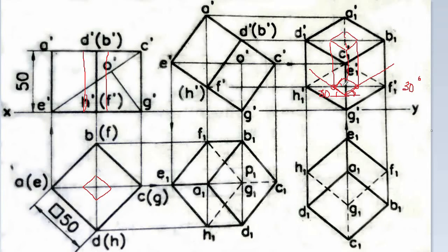After that, you take another 30 degree line. This angle is 30 degrees, and you can draw another two lines in both directions. Then you can project upwards, and you can mark the height. What about this height? This height will be 0.816 times the actual height, and you can mark these four points. After that, you can connect them, and you can obtain the final elevation.